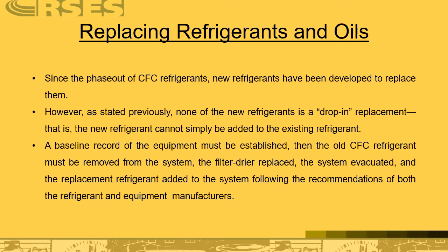Replacing refrigerants and oils. Since the phase out of CFC refrigerants, new refrigerants have been developed to replace them. However, as previously stated, none of the new refrigerants are a drop-in replacement, since the new refrigerant cannot simply be added to existing refrigerant. The baseline record of equipment must be established, the old CFC refrigerant must be removed from the system, the filter dryer replaced, the system evacuated, and the replacement refrigerant added to the system following recommendations of both refrigerant and equipment manufacturers.